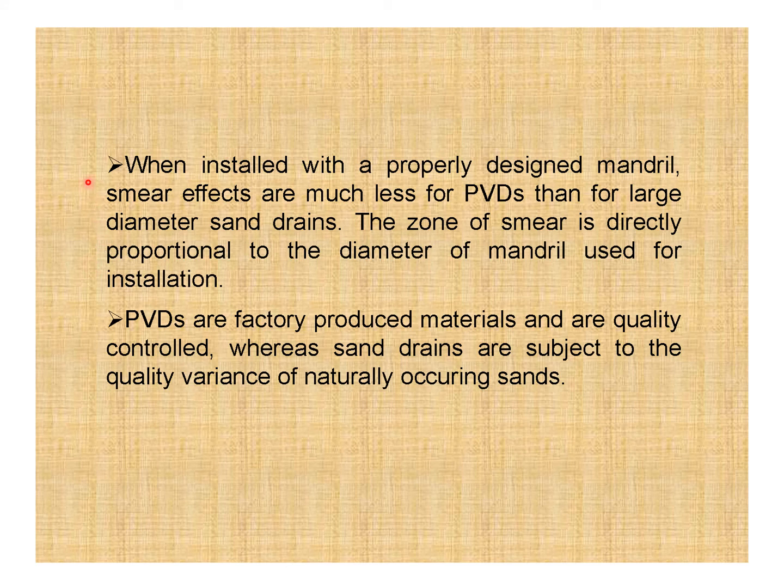When installed with a properly designed mandrel, smear effects are much less for PVDs than for large diameter sand drains. The zone of smear is directly proportional to the diameter of the mandrel used for installation. PVDs are factory produced material and are quality controlled, whereas sand drains are subject to quality variance of naturally occurring sands.